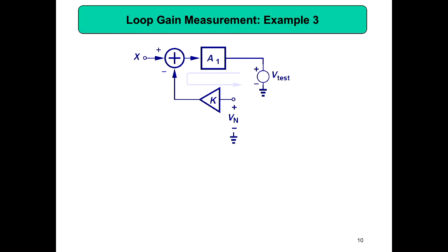So you are connecting signal to the collector, then you are going to measure something at the base. Will something come? You won't get anything, because usually the amplifier, all the circuits are designed in such a way that from output to input nothing will go. Only input to output signal will propagate. If something propagates into the input, then your device is faulty. So you can't pump signal from output to the input.